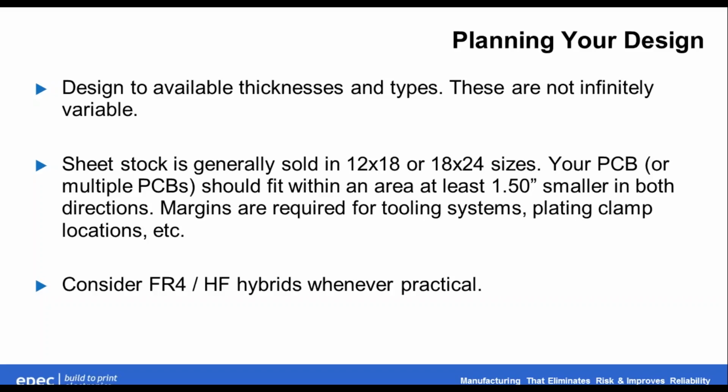It's kind of a sacrificial area that's required, but obviously you need to fit your board to the device it goes into as your first priority. But if you can shave a little off or make it a little bigger or whatever and fit it so that it fits those panel sizes, just be aware that they are what they are. And again, as I said before, consider FR4 and high-frequency hybrids whenever that's practical, because that will save you a ton of money in some situations.